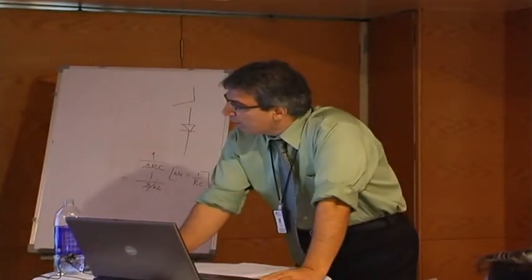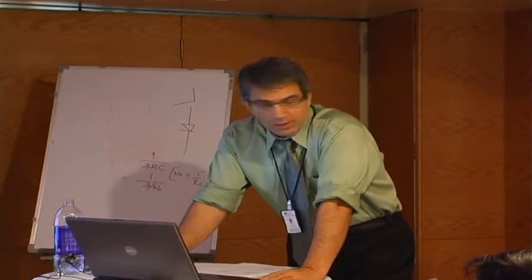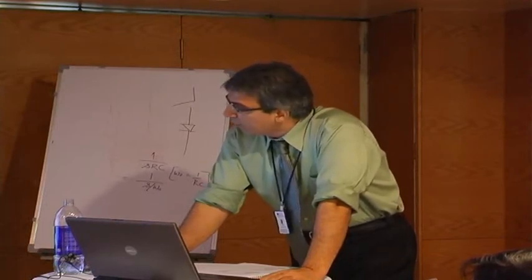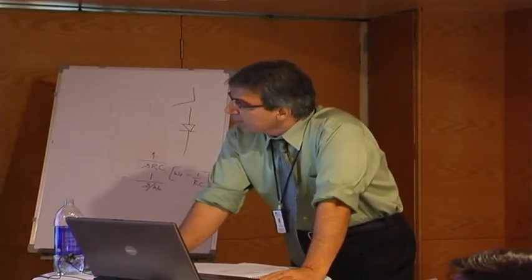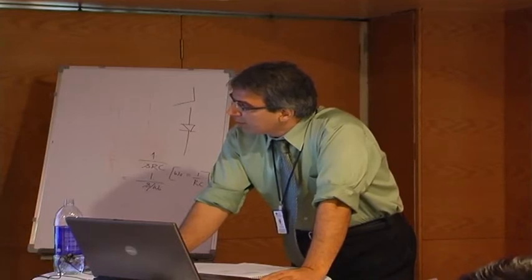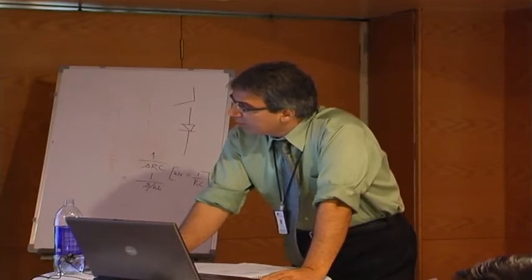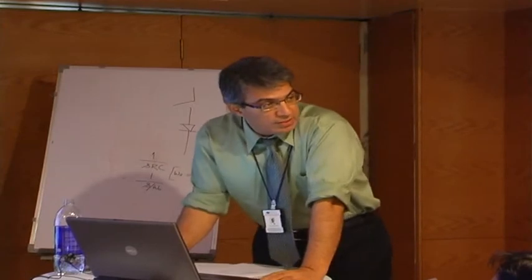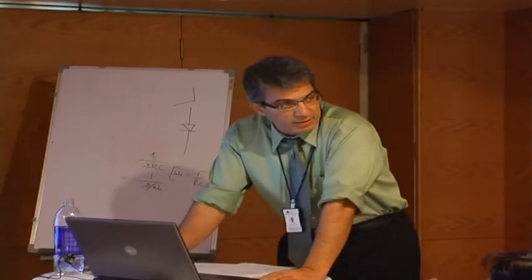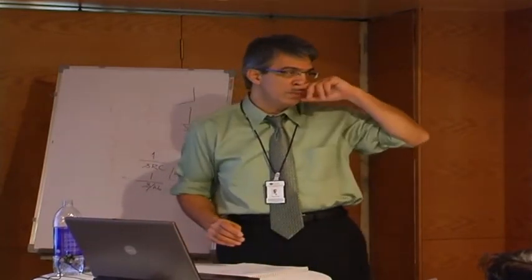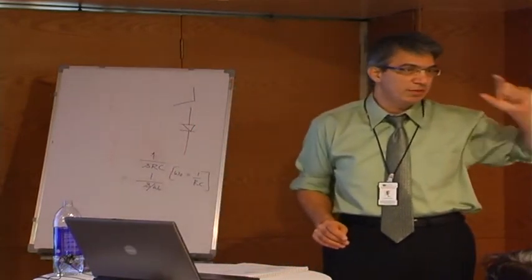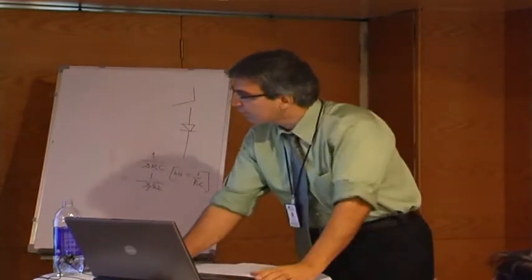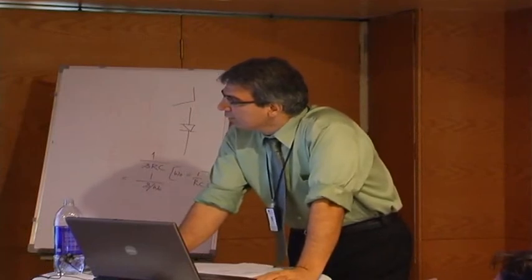And then you also have an option of changing the algorithm. If you look at advanced options, the simulation algorithm you can change. You basically have 0 or 1, default, 0, 1. Essentially you have the three options. But I don't think there's a difference between default and 0, because as far as I know, there are only 2 algorithms used by PSpice: Newton-Raphson, and the modified Newton-Raphson method.